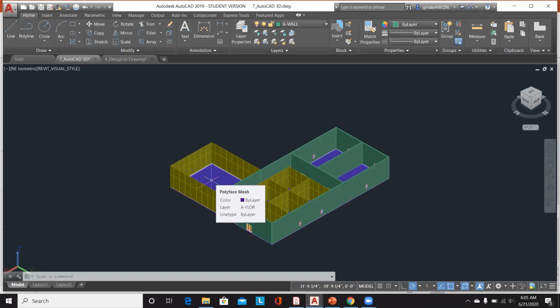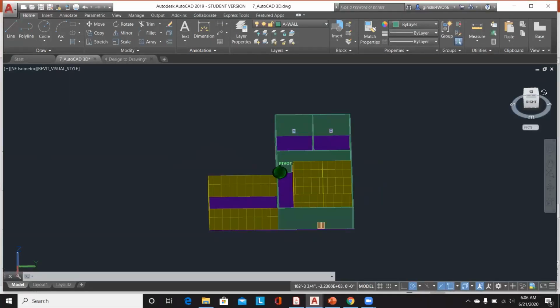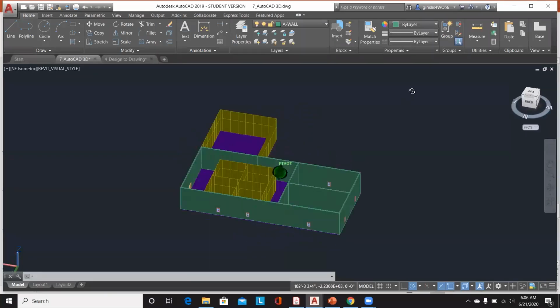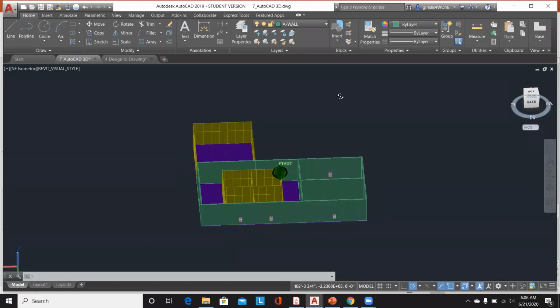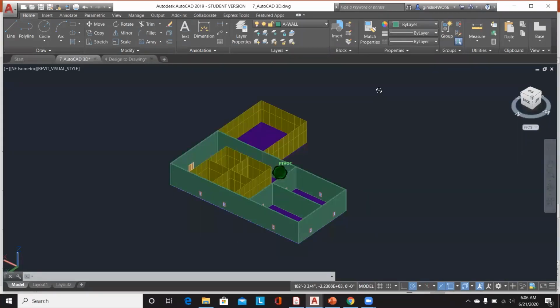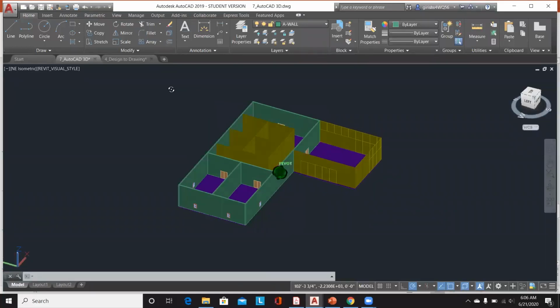And you can use your mouse to rotate your model instead of just clicking on the view cube. When you hold right click and rotate your mouse, there's a pivot icon that appears in the center, and the model rotates about the center that you create, and that lets you walk through how your model looks from a 3D space.